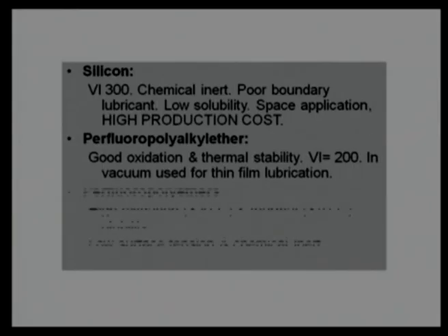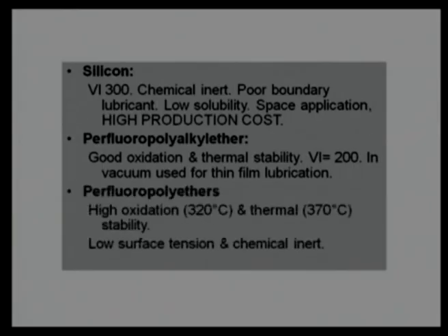There is a similar kind, the perfluoropolyalkyl ethers, perfluoropolyethers. Their VIs are high, they have very good thermal and oxidational stabilities, and can even be used in vacuum applications. The temperature limit for perfluoropolyethers is 320 degrees centigrade, same as silicon oil. They are also chemically inert.